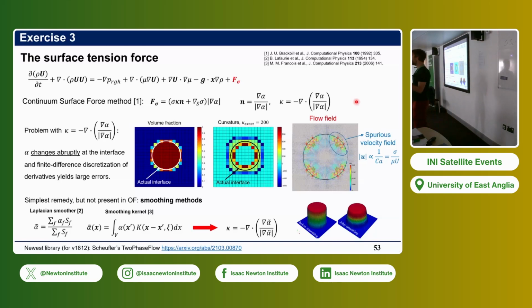In an ideal case, when you run your simulation, this is a Young-Laplace problem. Nothing should happen. If there is no gravity and no external flow, your circular interface should remain there forever, never moving. If you use Basilisk to solve this problem, that's more or less what happens, because Basilisk is fantastic at calculating all these terms.